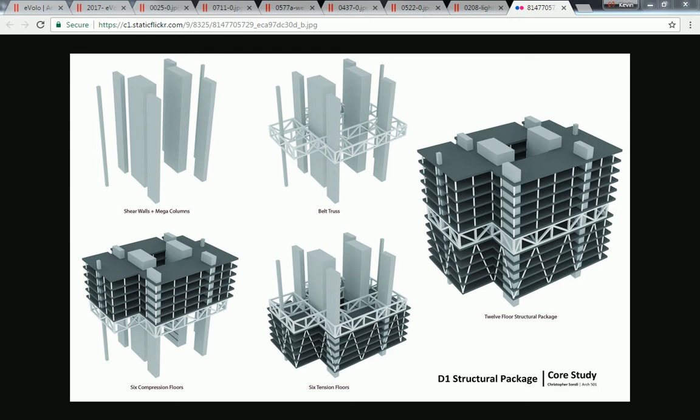So what we're going to develop is a series of masses, and we're not really going to delineate right now between elevator and stair and everything like that. We're just going to have a central core. We're going to understand what it's like to develop many floors in a Grasshopper mass, and then we're going to start to study how we might develop skin from that. That's all for the first week here, I think. So I'm going to introduce the floors and the mass on the outside here today, and then next week we're going to look at breaking things down into a little bit more detail to give us something to work with later on when we get to facades.